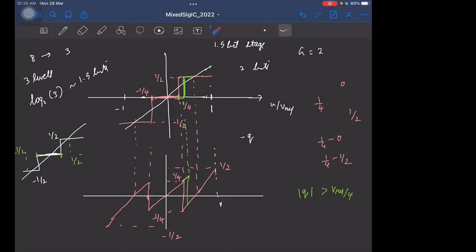So I think one of you had asked this question, right? So here the quantization error is going to plus or minus half. But that is okay because if you use a gain of 2, this is still within plus or minus VREF. Our original goal was that if there is any error in the comparator threshold voltages, we want to make sure that even in that case scenario, amplified quantization noise stays within the bound, right?